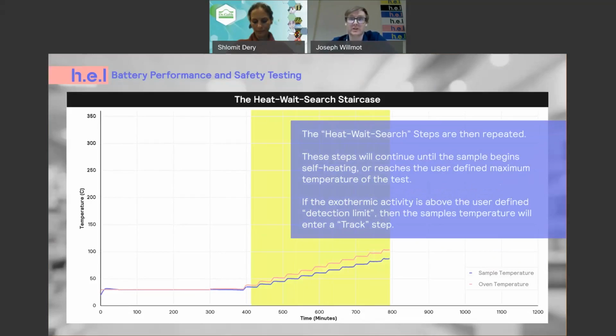Now, there could be multiple reasons why the cell starts to fail. This particular point of cell failure could be the puncture point that you decide to pierce your cell at. It could be that this is the temperature that the separator between your anode and cathode starts to fail, starts to melt. If that is the case, then we know of cell manufacturers who have started making separators that actually block the transfer of lithium ions and therefore eliminate the possibility of a secondary thermal runaway.